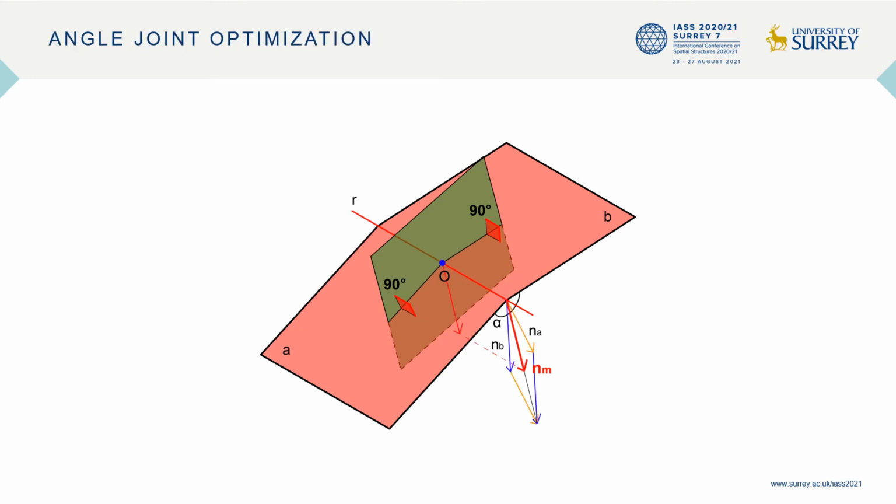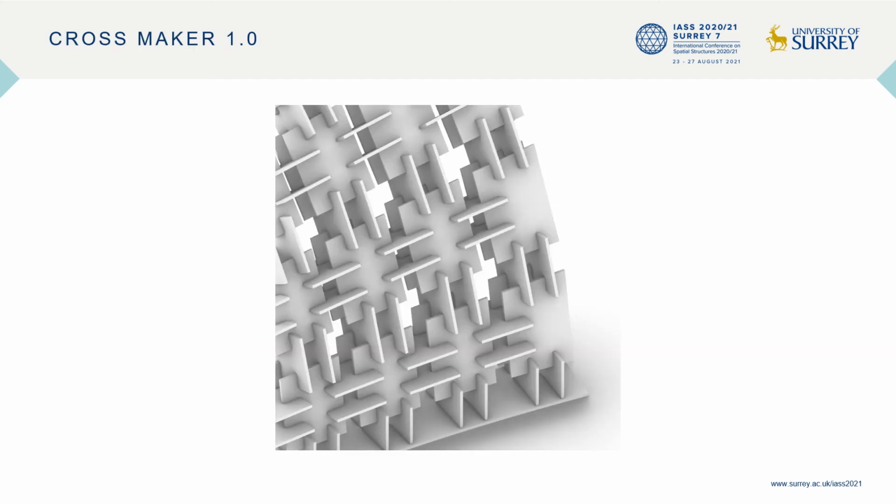The panels of the second frame were subsequently oriented by detecting the mean vector between each pair of the panels of the first frame, that is the resultant of the sum of normals belonging to both planes. The structural framework that is determined with the new optimization is therefore slightly different from the previous one, since the elements of the second frame are now perpendicular to the edges shared by each pair of contiguous panels.